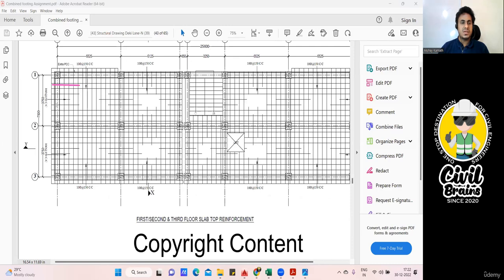Okay. This is calculated. Everything we got. We found we have to provide 48 bars in this direction, and the cutting length will be 2050 of this. Fine. Now you can come to the center and do the calculation. Else you can go to the corner and then come to the center. It's totally up to you to decide which way you want to go. What I'll do is I'll go to the corner now.